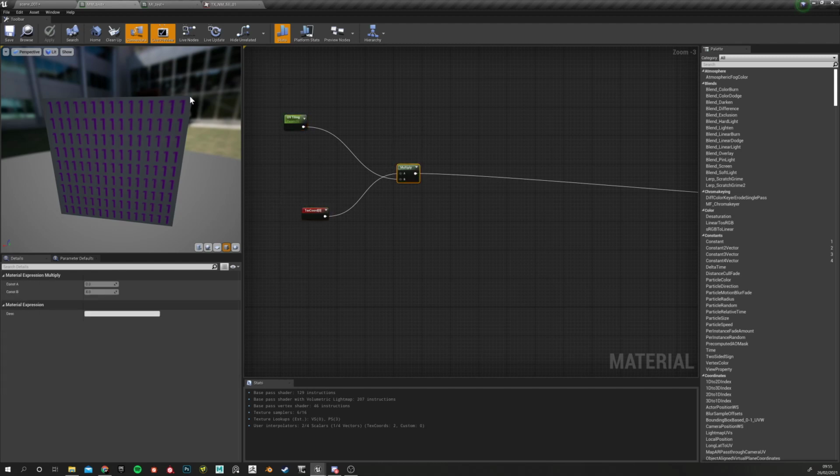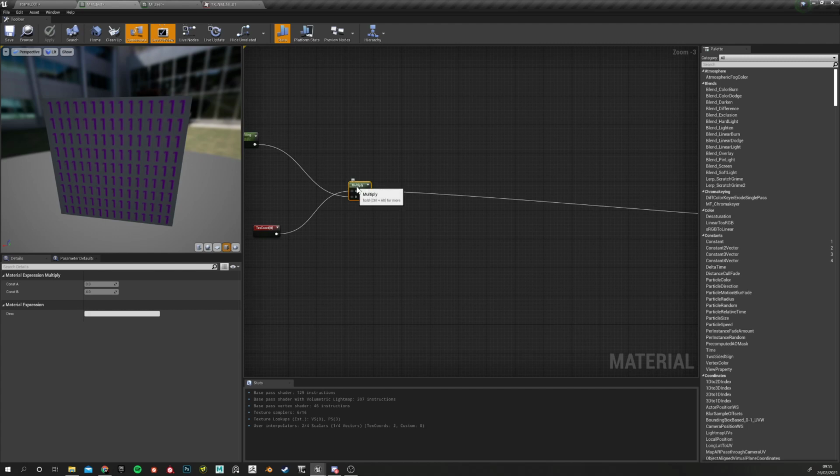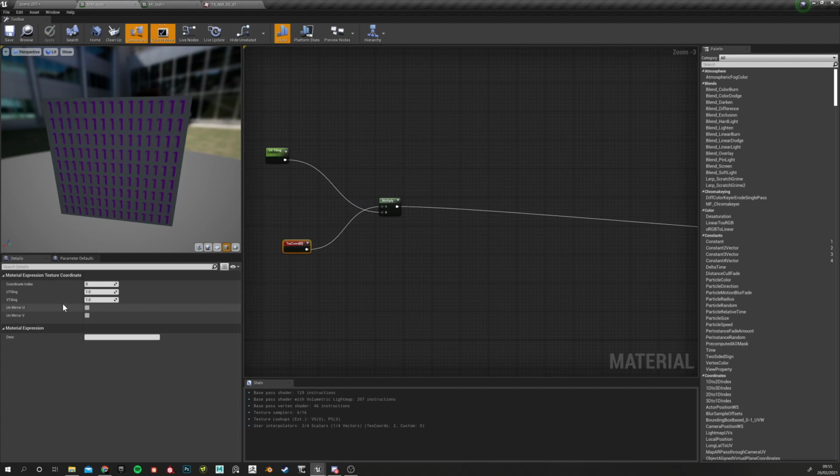If you want to multiply something by 0.5, we'll put it right here, which makes everything bigger because you're covering less space now, and then the UVs will be bigger. And if you multiply by 2, then you can put more stuff into a single 0 to 1. If you want to add an offset, then you have to add numbers to it.